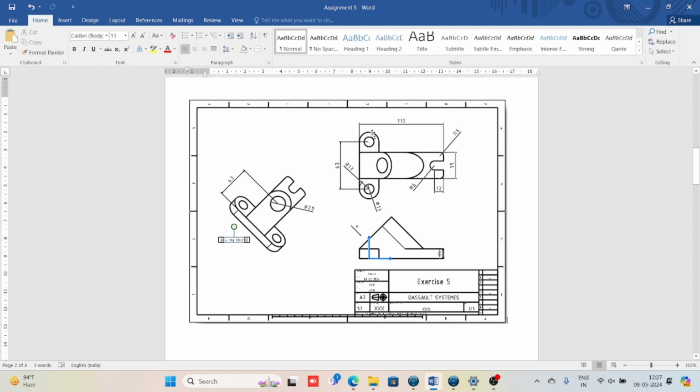So I'll take this elongated profile center as 0 0. Clear? And I can see that the complete drawing is symmetric about the horizontal axis. And I will take this axis as the vertical axis. So here my 0 will lie. So first of all, I'll just create this elongated profile.